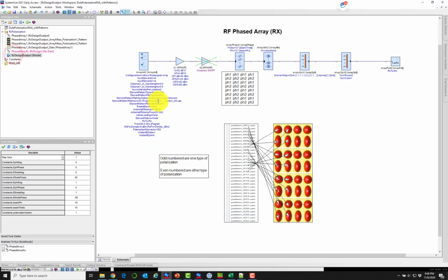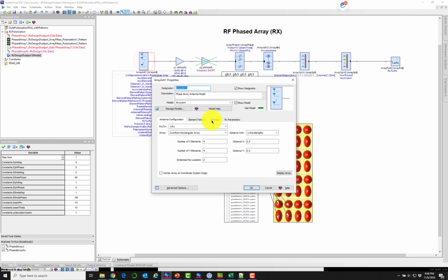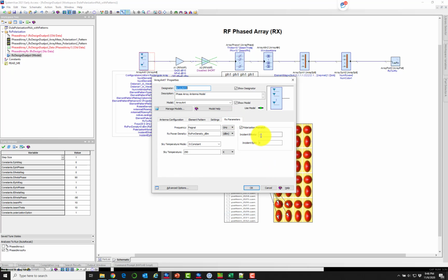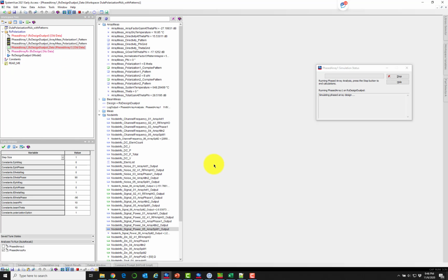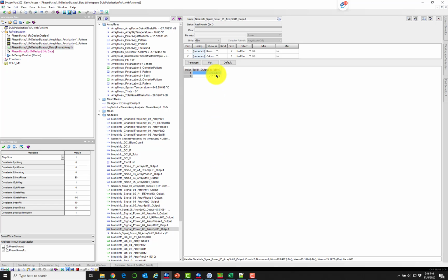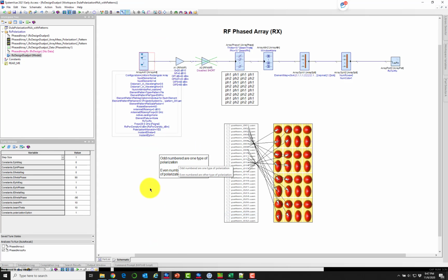Now, in order to verify if the E phi antennas are also going to respond to an incoming wave, we can reverse the polarization of the incoming wave and see what happens. Now you see that the roles are reversed. The E theta antennas together produced very low output, whereas the E phi antennas produced the correct expected output here. So from this, we can see that we have very successfully defined a dual polarization in the system.